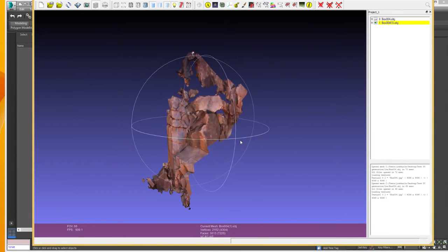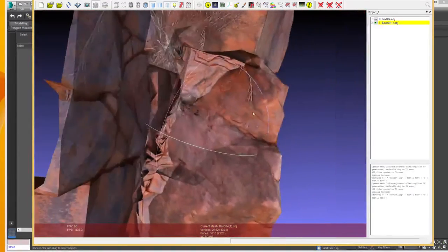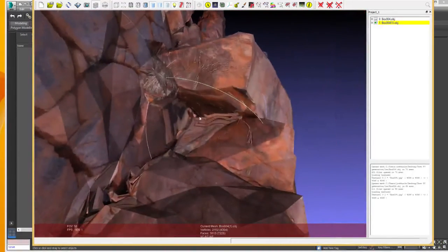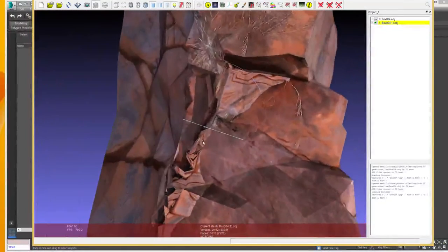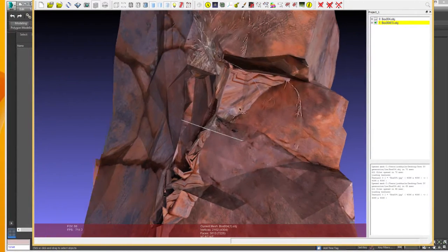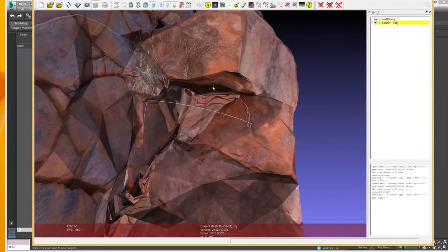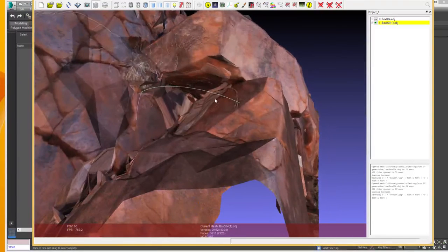Okay, so if that ray distance is too high, then what happens is when it's projecting the texture from this side, you get these weird artifacts in the corners, pretty much where there's one face that's sort of obliquely looking at another. What's happening there is that it's casting the ray out, and rather than just getting to the point where it hits the high poly mesh, it goes all the way down onto the facing model and casts some of the texture from this side onto that side.